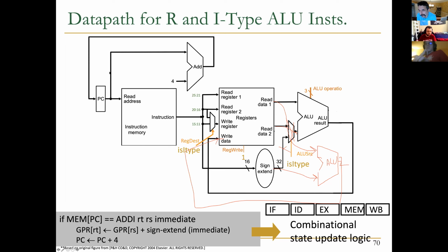Yes, I mean in single cycle microarchitecture, maybe not, right? But in multi-cycle, since you have two ALUs, an I type and R type, you can make the data path totally independent. Maybe you can execute them, and if these two instructions are not interdependent in your program, and you can figure it out some way, you can execute them at the same time, right? You can execute them in parallel, right? Because you have two ALUs, you can execute them in the same cycle, assuming that you are able to execute things essentially in parallel.